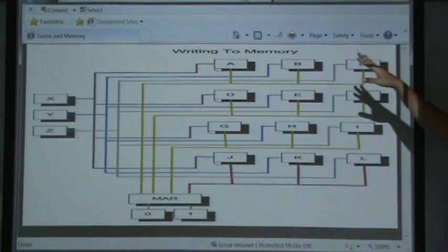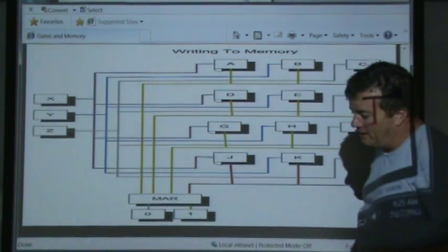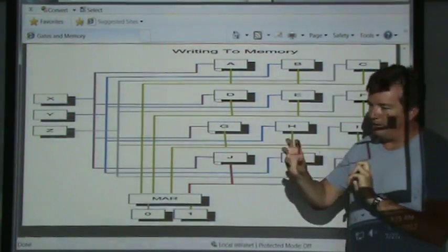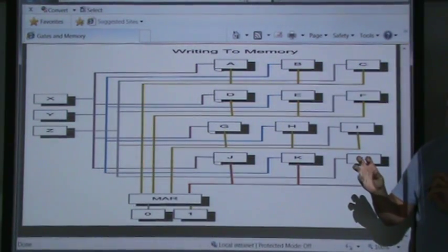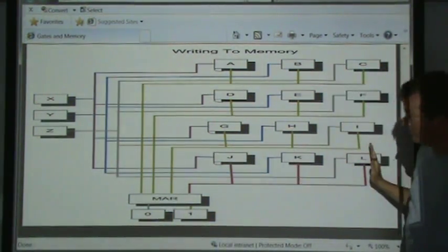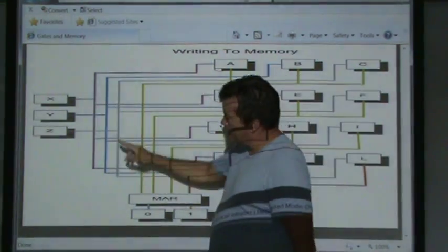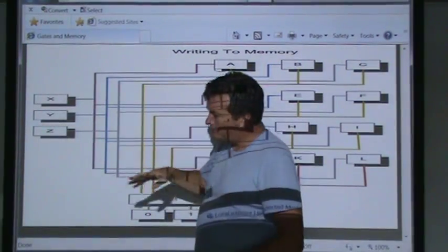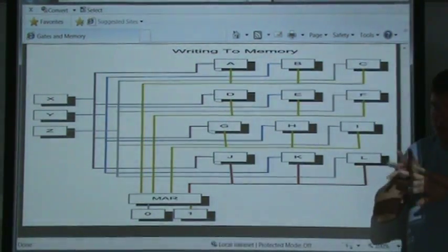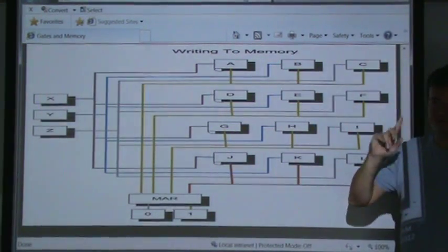And then we have to put all this wiring around it just to be able to open up some memory and not other memory. So when we read and write from memory, what we're really doing is, out of our entire memory board, we're picking an address, we're putting bits on an address bus, and we're telling the memory to lock out every memory cell with the exception of the one we're trying to write to.